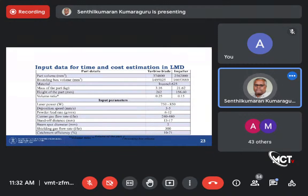So whatever material goes into that, divided by the total material supply, is given by the catchment ratio or catchment efficiency. That will depend upon the stand-up distance, and we assumed a very low value for some process parameters and a very high value for others. So you can just look at this. It varies largely from 10 to 17%. It depends upon many factors like the orientation of the surface with respect to the vertical direction, nozzle orientation, substrate orientation, so many factors. In fact, we have recently published a paper entirely on catchment efficiency, optimizing for thin wall deposition using LMD. That's a separate work. Maybe in some other talk we'll talk about it.